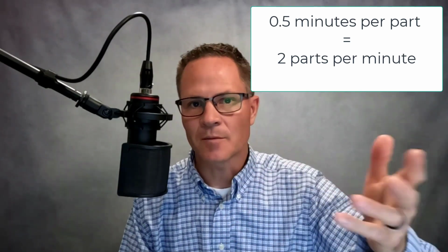Now, a lot of companies operate on a pitch of 1 hour, a pitch meaning a segment of time in which you need to get a certain amount of work done. So you can take your takt time, which is seconds per unit or minutes per unit, flip it over, and that will give you units per hour or units per minute, which you then multiply by 60 to get units per hour. So you can flip it and operate that way, look at your units per hour, but it's always good to know what your time per unit is so that you can go out and measure each of your processes, gather cycle times, and find out if each process step can actually hit the takt time.